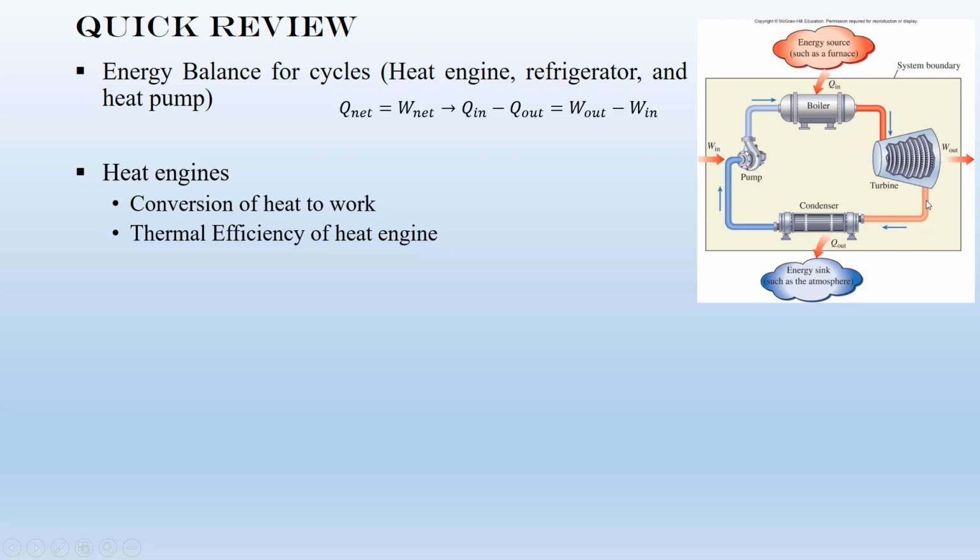The exit of this turbine normally is a saturated vapor, saturated liquid mixture, and then this mixture goes through a condenser, and heat is transferred from this condenser to the energy sink, and the exit of this condenser is normally compressed or saturated liquid. So this is the concept of heat engines.